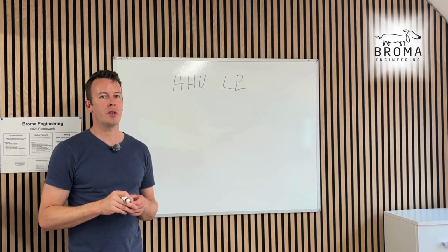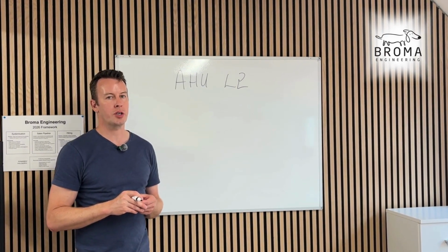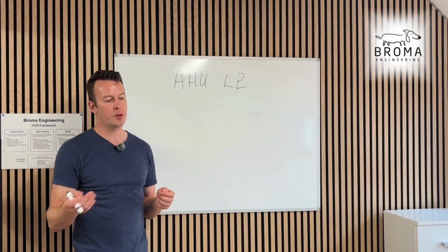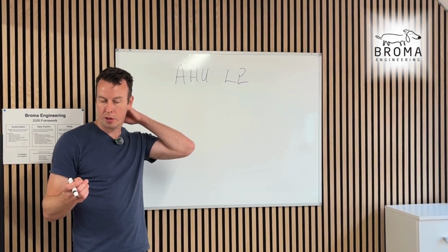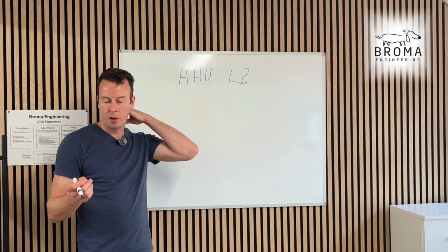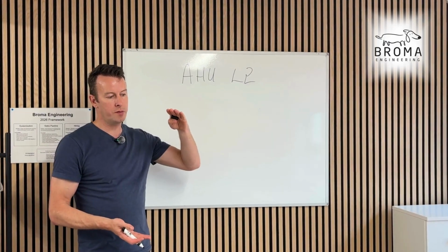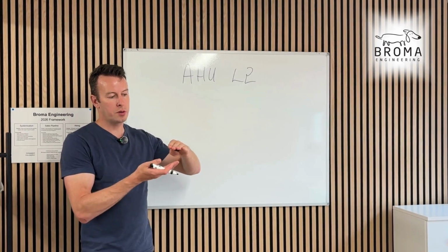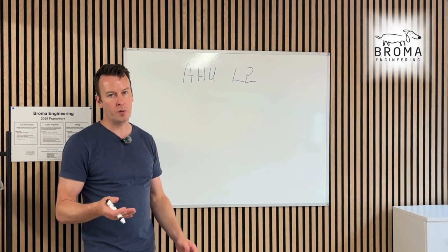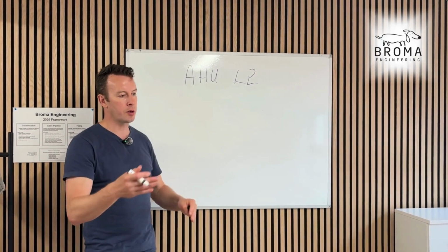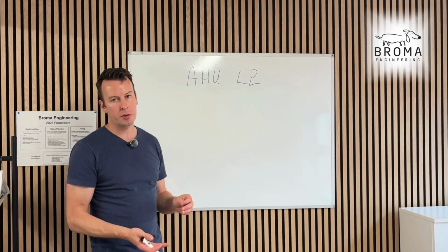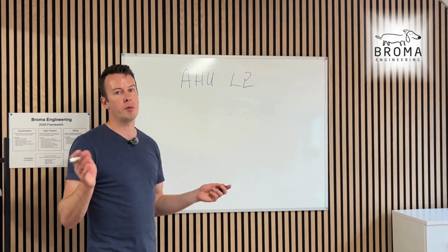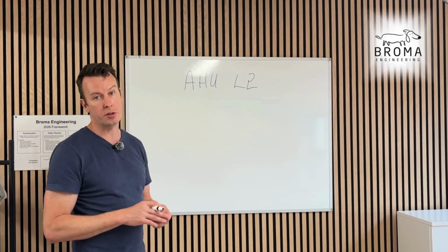Just a note on level 2 check sheets, or the main check sheet. I would have one main check sheet that references the other check sheets or references the other documents. So again, try to keep it simple. We want a number of documents to achieve yellow tag, and one of those documents is going to be the final inspection. You can do it that way, or you can have the final inspection and bake in the other documents into it. I think it's better to keep them separate, but sometimes the client is applying these check sheets to you, so you won't have a choice, and maybe you're better off not having a choice, because then the decision is easy.